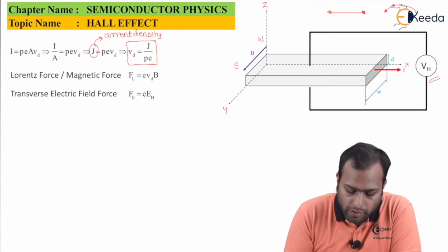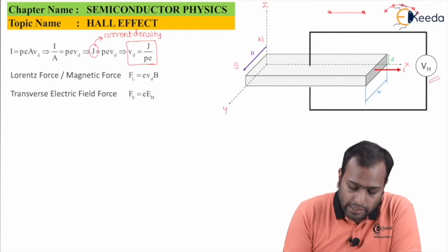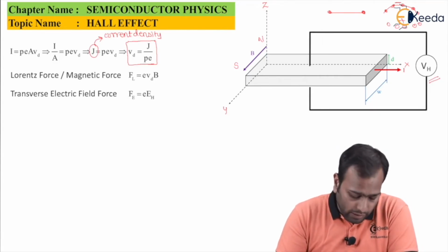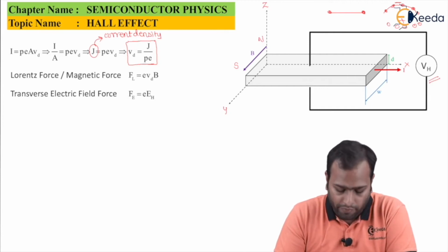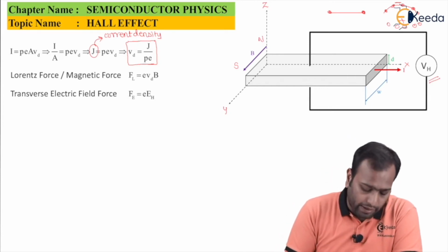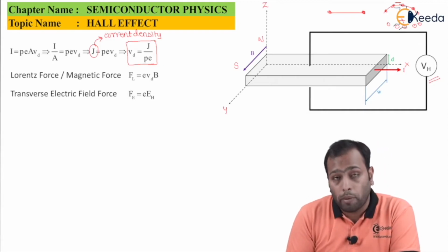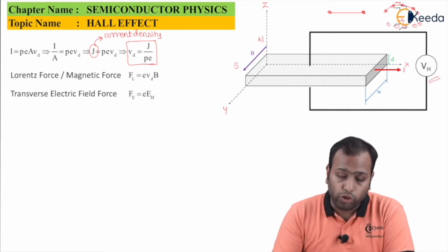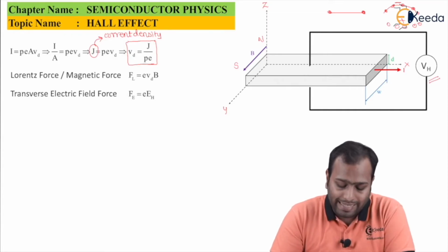The electrons were here, which creates electron density here, and of course the negative charge here, and holes here, which of course is the positive charge. This is what is called the transverse electric field. Another point to remember, this is the electric field which is transverse or perpendicular to the actual electric field. The actual electric field is not shown here, but it is represented as current I.